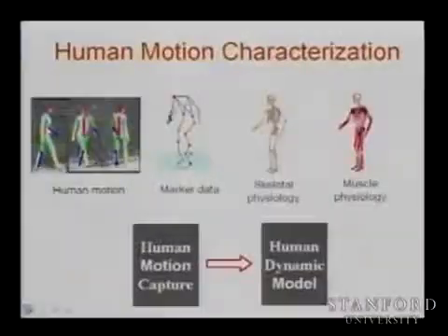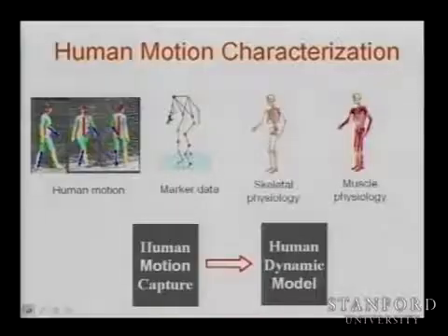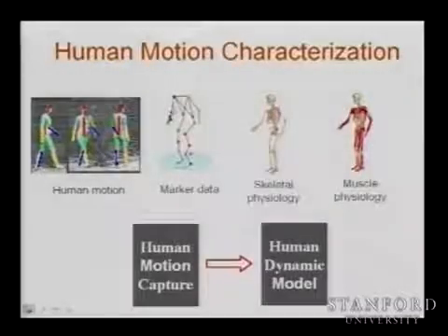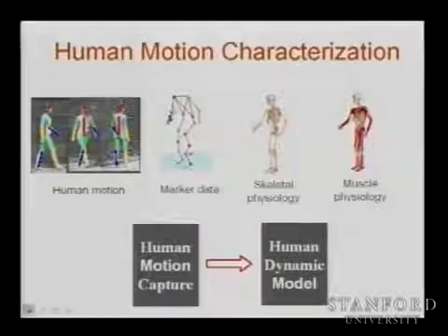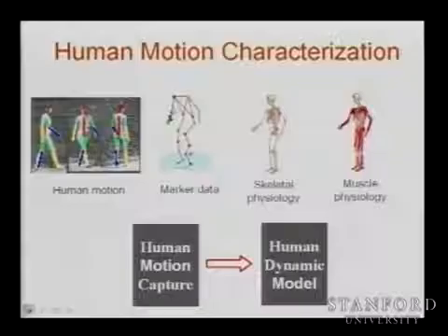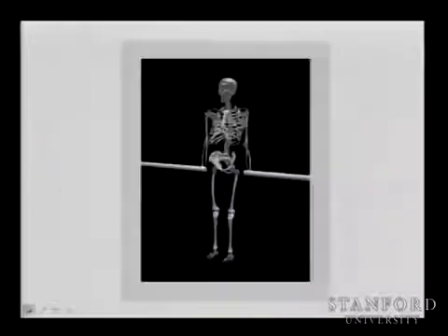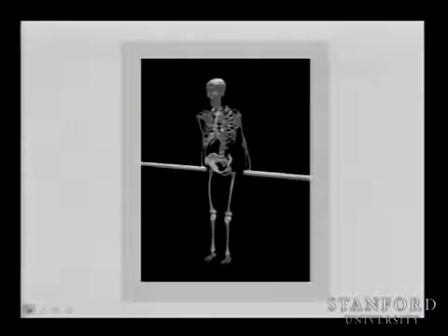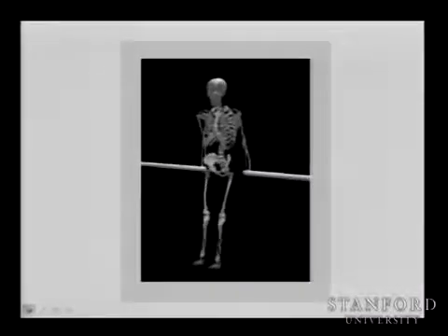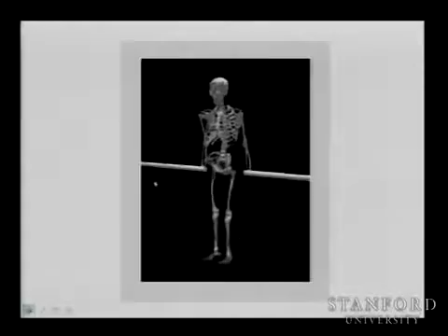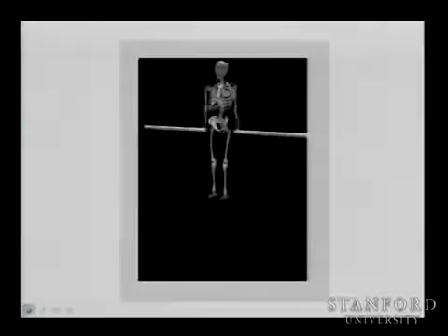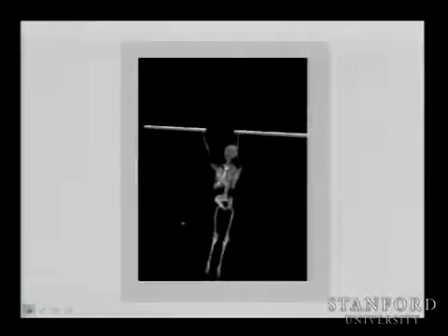I mean, it is really interesting. We were working with robots, and now we are working with human models. But human models are essentially articulated body systems. The mass matrix you computed is the same. You can use the same mass matrix. The actuation is different. So for the mass matrix, you can now take the rigid body part, the skeletal model, and now animate it. And this is what you see. In fact, drop it in the gravity field, a pendulum.